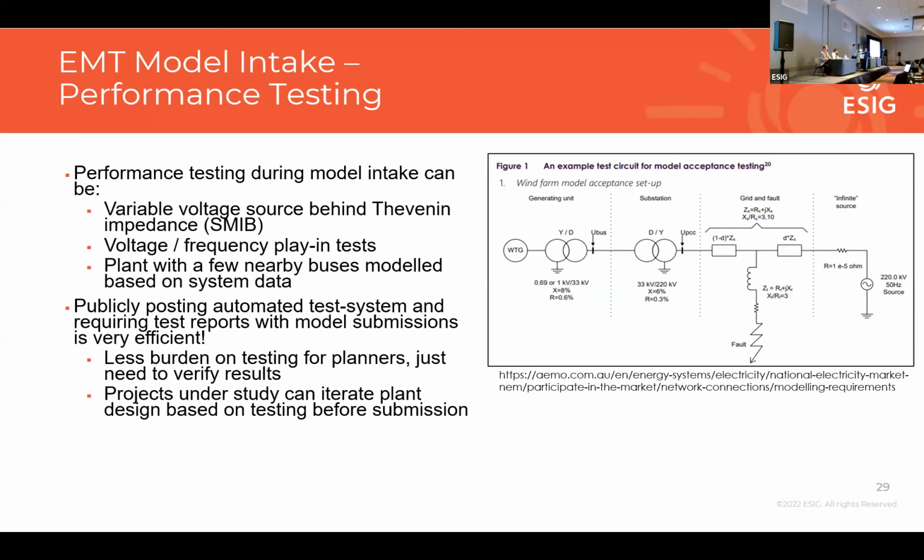And within that model, we can actually test a lot of things. We can test fault ride-through, voltage and frequency support, and performance in a number of different ways. We can do voltage and frequency play-in tests. So we can take that source and start playing around with the voltage and frequency and the phase of that source as well.